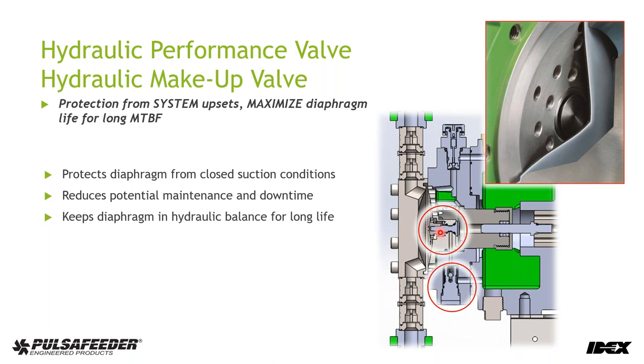So what does that mean for you? That means that this protects your diaphragm and your pump. It means that in the event of a closed suction condition, maybe someone's closed a valve downstream, the likelihood that these critical components of your pump are going to fail is significantly reduced.